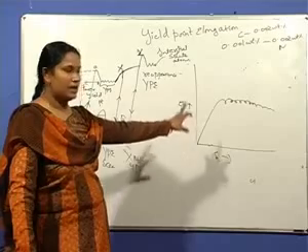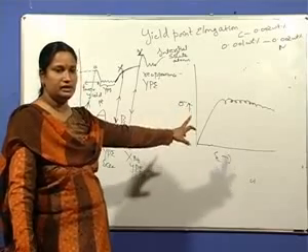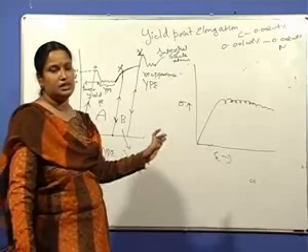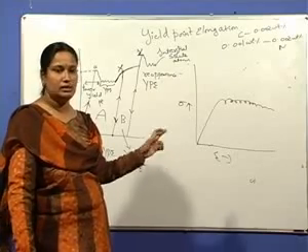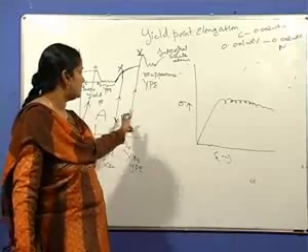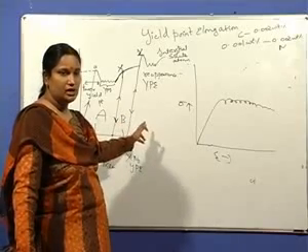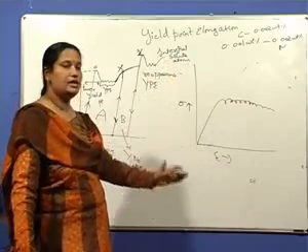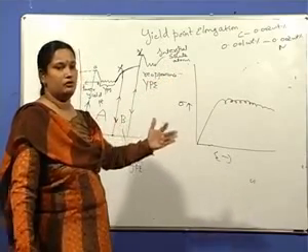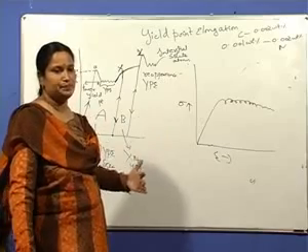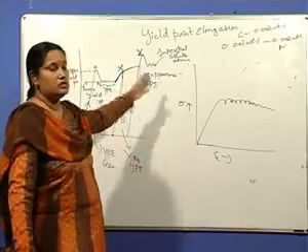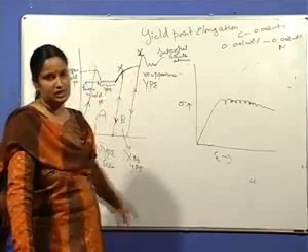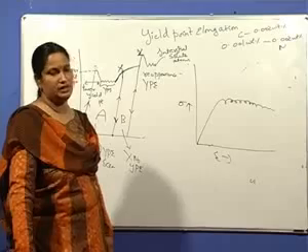So this effect is not seen at greater than 400. This is at slightly higher temperatures, 200 and 300 degrees centigrade, and when strain aging occurs during plastic deformation, it is known as dynamic strain aging. And this is static strain aging, where the material is loaded beyond the yield point, unloaded, and again given some time for the diffusion to take place, then reloaded. So the reappearance of the yield point is seen at slightly higher stress. So this strengthens the material.